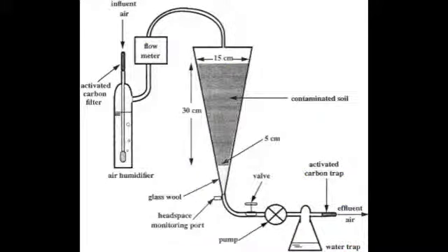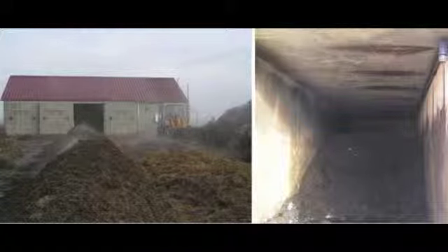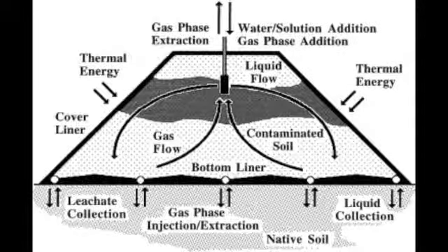Controlled solid phase biotreatment involves processes that include treatment beds, biotreatment cells, soil piles, biopiles, or composting matrices where moisture, heat, nutrients, oxygen, and pH are controlled to enhance biodegradation. These processes are often enclosed to control expelled gases and include a leakage collection system and some aeration. This technique is among the expensive ones when applied.